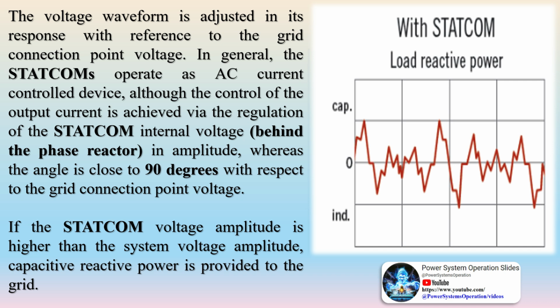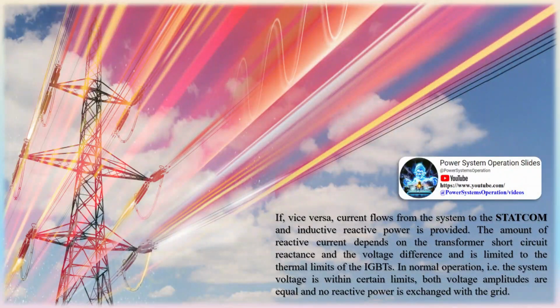The main advantage of the STATCOM for improving transient stability lies in its ability to quickly control bus voltage. Specifically, the STATCOM can enhance power transfer during low voltage conditions, which are common during faults, thereby reducing the acceleration of local generators. Additionally, it helps mitigate the demagnetizing effects of faults on local generation.